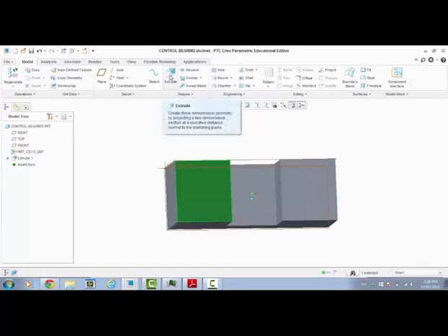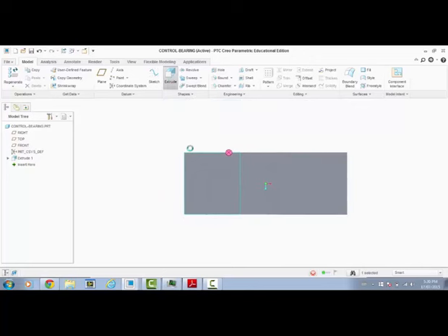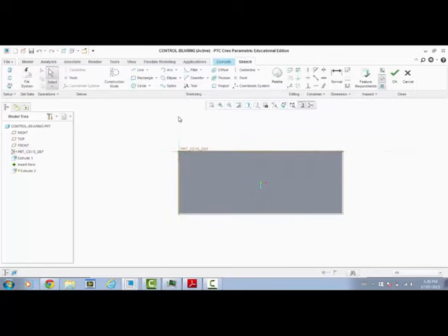Just click it with the left button of your mouse. We click extrude, and now this comes up. The blue lines are reference lines that we need to draw on. If we go to line, we cannot draw on this gray edge. You just can't snap to it, but you can snap very easily to the reference line.